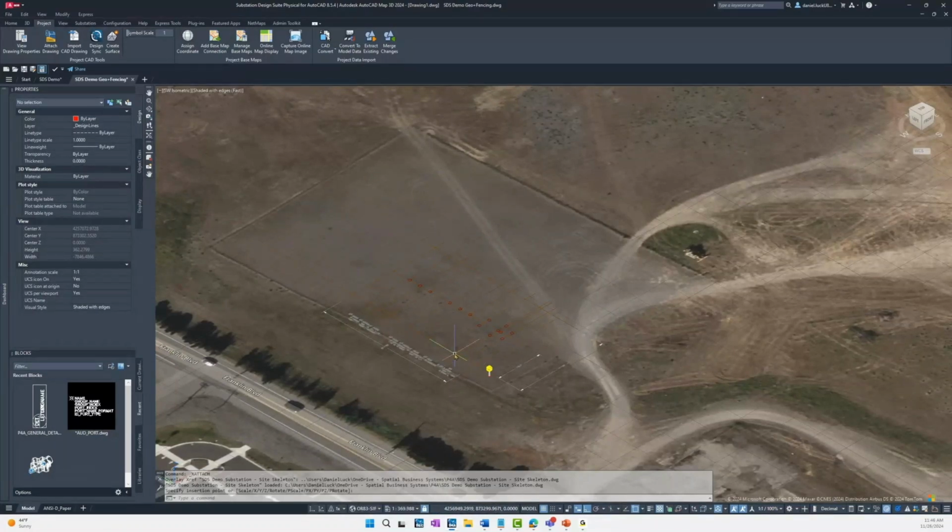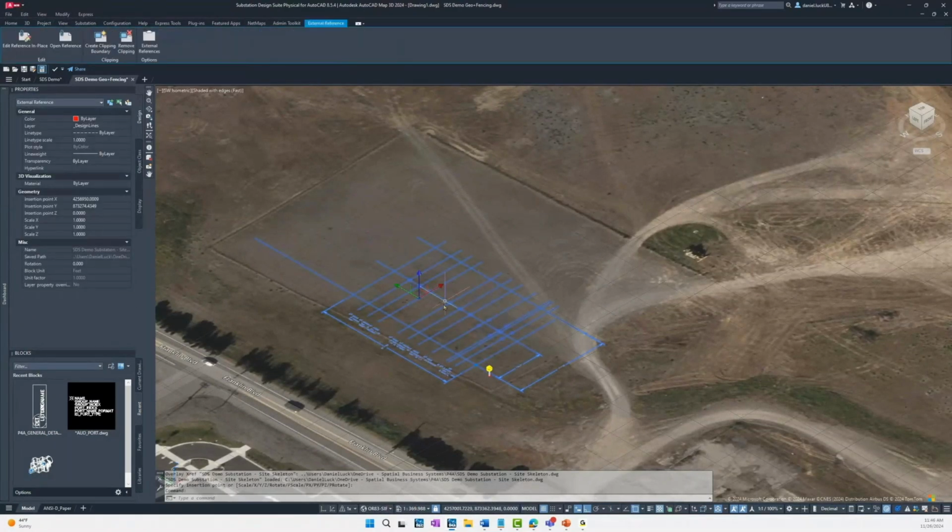Just a quick note about that XREF command. It's dynamic, so any changes made to the remote file, so as if you were to modify this externally referenced file remotely, it will get synced in almost real time, providing instant updates, which is fantastic. So you can have someone working on that separately and have it update your main project design